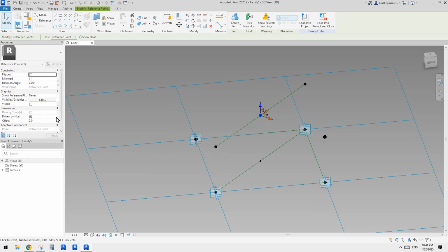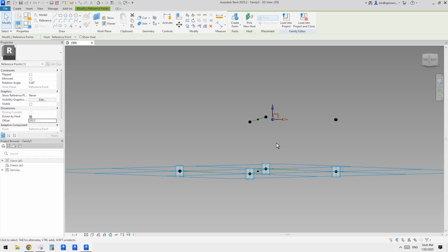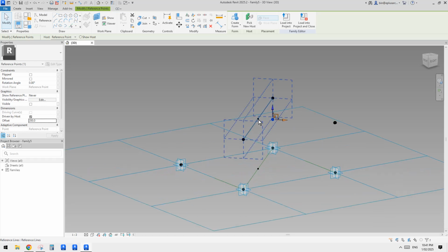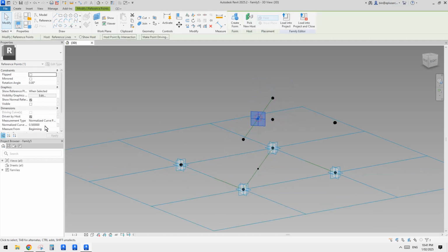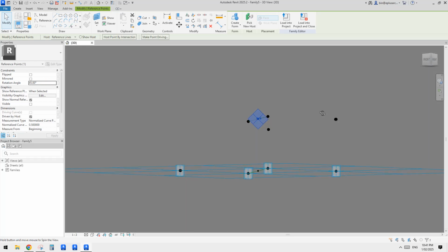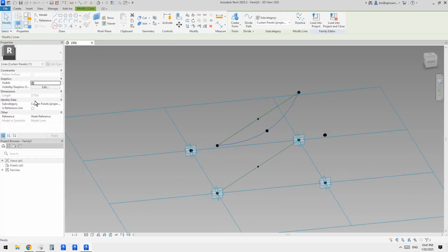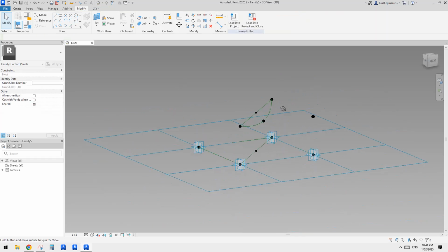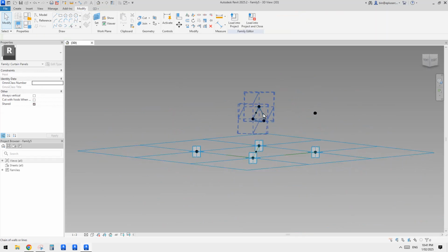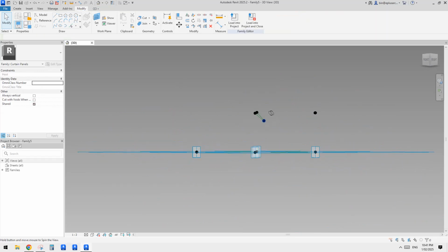So now select this point, we can offset it. So for example, 200. And then because we want it to be roughly here, we can just rotate this point by roughly 45 degrees. Okay. And then we can connect 1, 2, 3 and create a spline through points and use reference line. Now we have this line, sitting relatively closer to here, right?